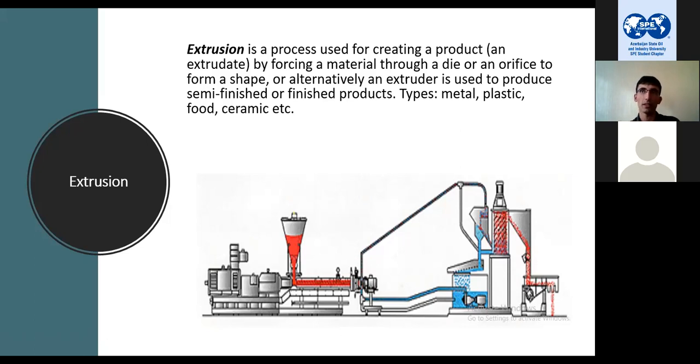The die plate is like a circular metal plate with many small holes on it. The melt flows out like spaghetti, and as it goes out, it meets cold water, which solidifies it, and then it meets rotating knives, which cut it.